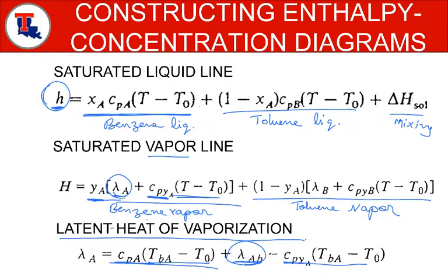Look at the amount of heats and enthalpies it's considering. How extensive this method is compared to the McCabe-Thiele. The McCabe-Thiele is really a back of the envelope calculation. This is not. And when you take into account many different things, the calculations become really difficult. And hence, you can find the enthalpy value. Your first aim should be trying to find these enthalpy values from journal articles, Perry's handbook. Even this book has some enthalpy, small h and capital H is given. There are so many other textbooks. Try to look for that data when you're doing design.